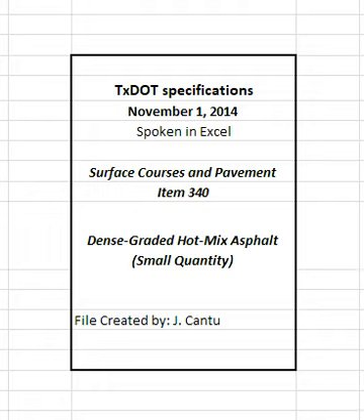2.7 Recycled materials. Use of RAP and RAS is permitted unless otherwise shown on the plans. Do not exceed the maximum allowable percentages of RAP and RAS shown in Table 4. The allowable percentages shown in Table 4 may be decreased or increased when shown on the plans. Determine asphalt binder content and gradation of the RAP and RAS stockpiles for mixture design purposes in accordance with TEX 236F. The engineer may verify the asphalt binder content of the stockpiles at any time during production.